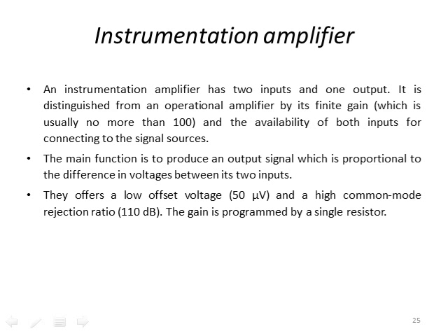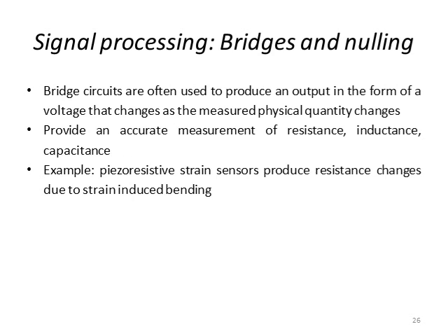And interestingly enough, the gain can be basically set by a single resistor for these systems. They're very powerful, so you should be aware of them for doing sensitive and robust measurements. Sometimes an instrumentation amplifier is a little more expensive, but it can provide much better performance than a single operational amplifier.